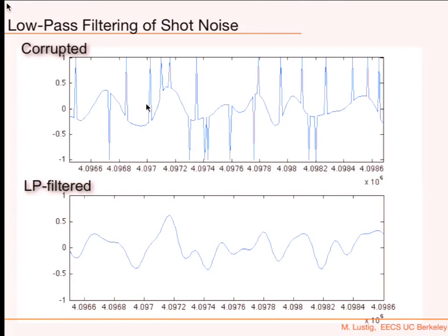Oh, threshold. So you do a kind of moving threshold and see, oh, there's a spike here, and I need some way to estimate what's in between. Then maybe I could do a linear filter, right? But then it's definitely nonlinear because I need to figure out a threshold and then do different filters for different parts, right? So that's an adaptive kind of filter, okay? But definitely I can do something else than just using something linear, right?